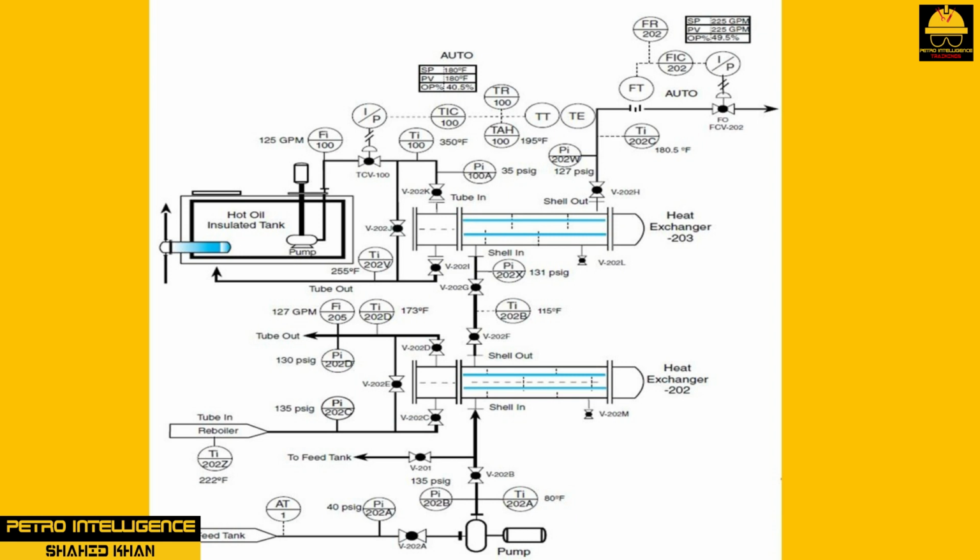Exchanger 202 has a longitudinal baffle running through the center of the shell. This partition forces the feed through a series of lower baffles to pass across the body of the heat exchanger one time before entering the upper section of the shell and moving back across the body of the exchanger and through another series of baffles before exiting through the shell outlet.